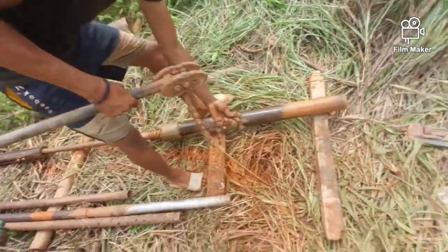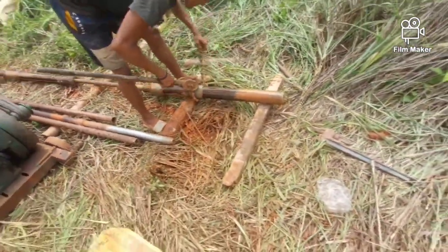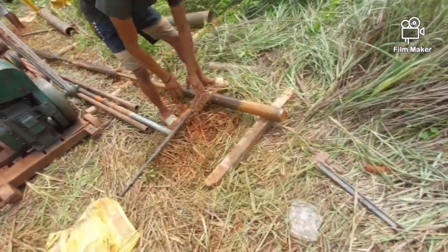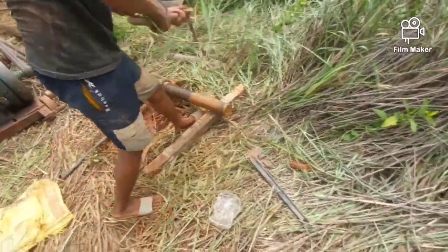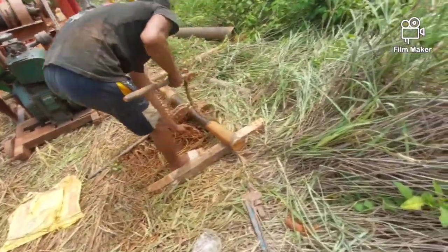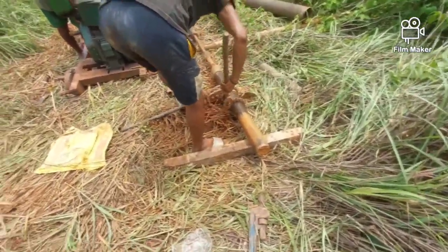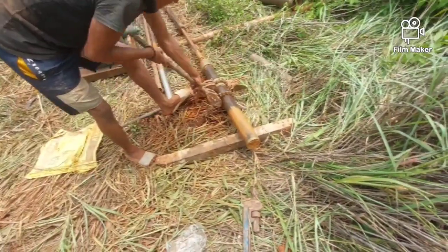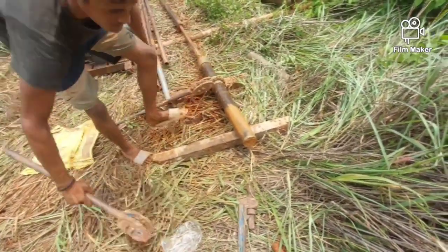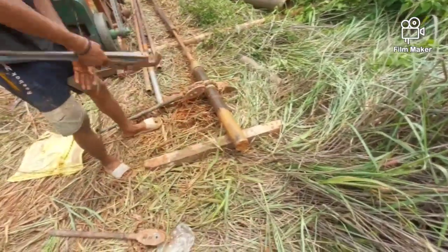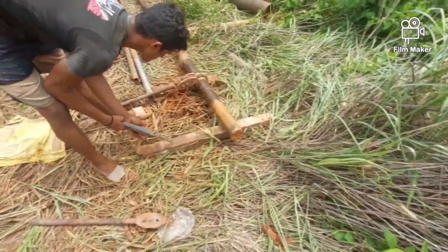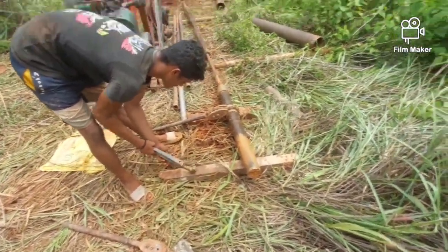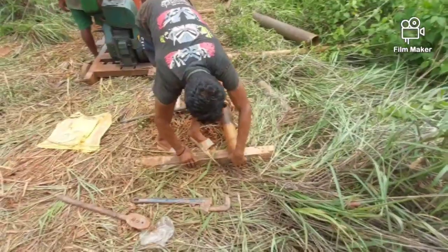Here this is a cell undisturbed soil sampler barrel, and it will be removed from the rod with a wrench. Also after removing the undisturbed soil sampler, the sample will be collected from the core of the barrel.